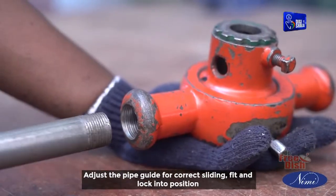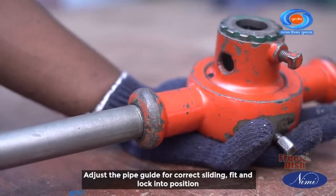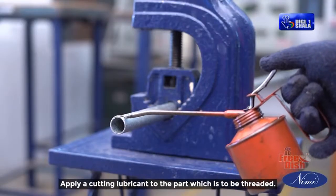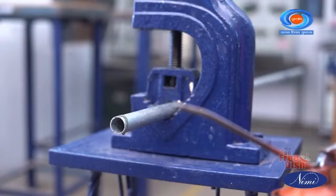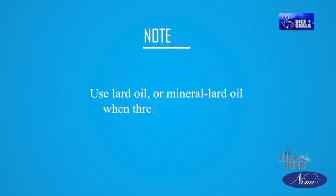Adjust the pipe guide for correct sliding fit and lock into position. Apply a cutting lubricant to the part which is to be threaded. Note: use lard oil or mineral lard oil when threading GI pipes.